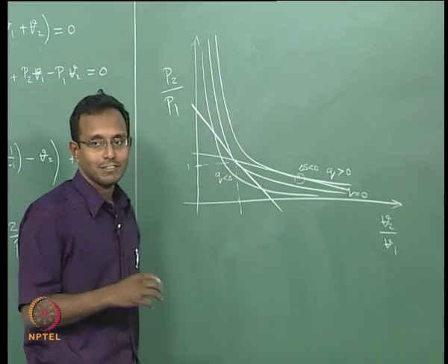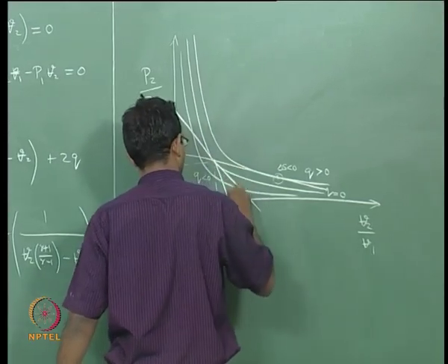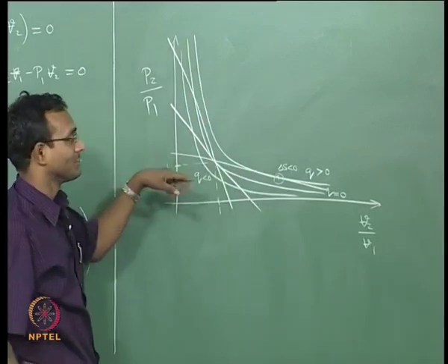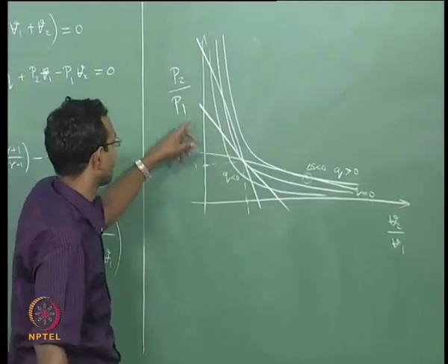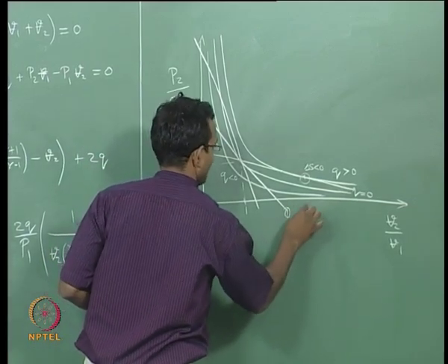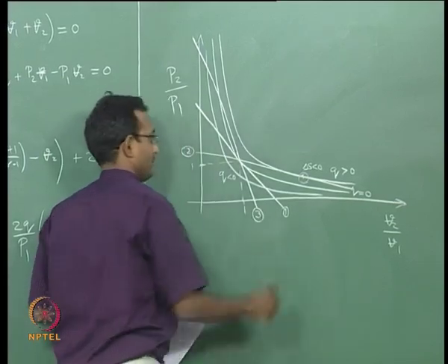Now, if I consider a very high Mach number, that is supersonic Mach number, this will give me this kind of a curve. I am drawing too many curves here, I will go back to plots with colors later. I call this curve as 1, this Rayleigh line as my 2 and this Rayleigh line as my 3.